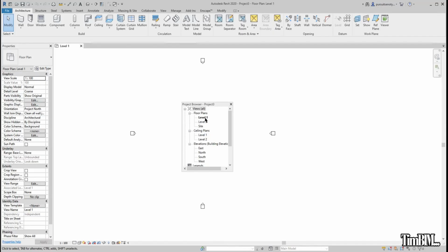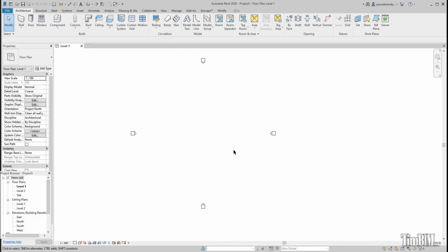So we have to customize these levels to our own preference, what we want. We cannot change these levels here because the levels cannot be seen on our floor plan worksheets. The only place we can do that is in our sections or our elevations. So we have to come here and open any of the elevations. So we have to click on the elevations.